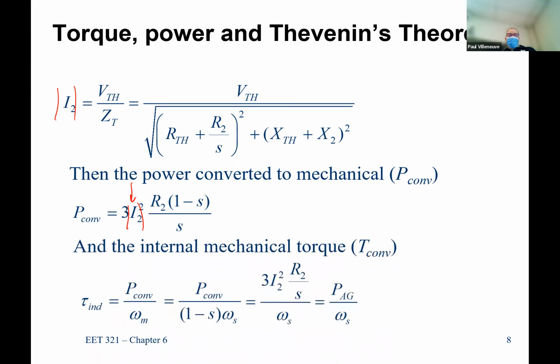And my torque is going to be either the converted power over omega sub M or the air gap power over omega sub S. Either one is perfectly fine.